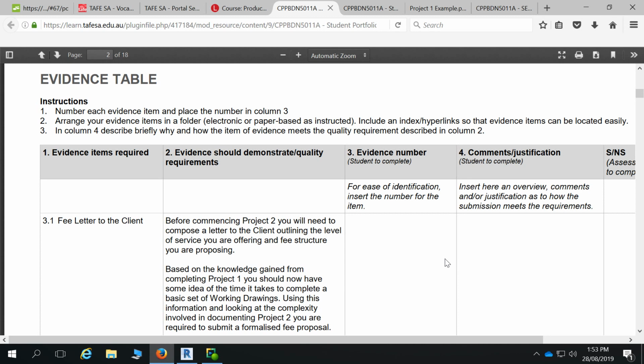So sometimes it's a matter of working out which side it's going to start on, which corner it's going to start on and go around, and also moving windows and doors slightly so that you reduce that 300 cut, because at some stage there might be a panel that finishes and you've got 200 to a window, and what's going to happen next to that. So you've got to work all that out, to try to minimise your small widths.